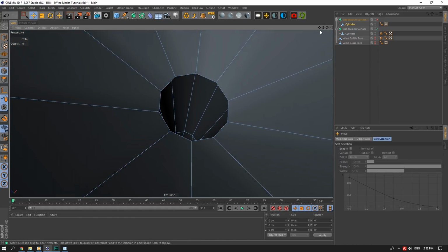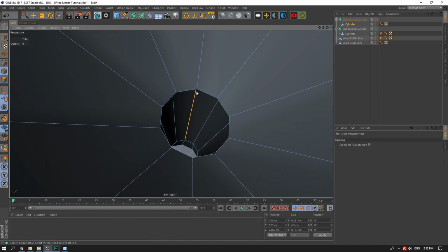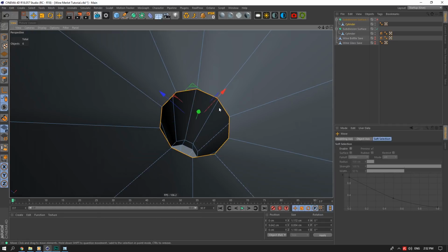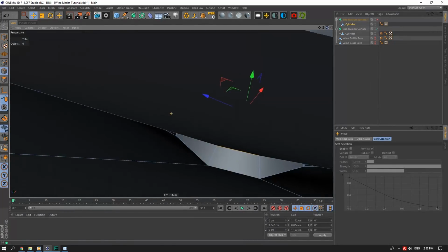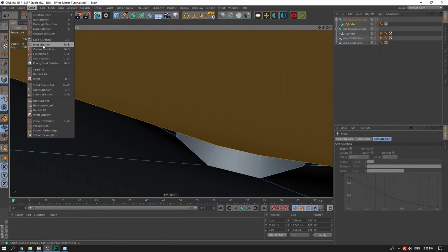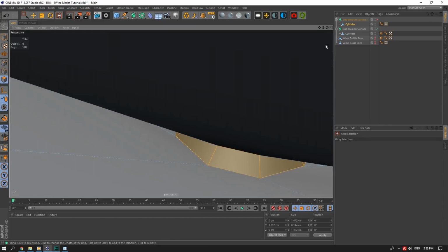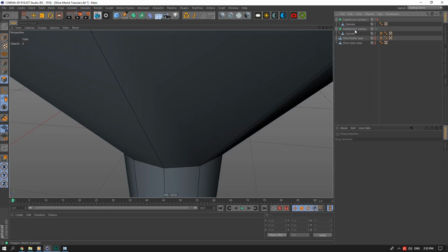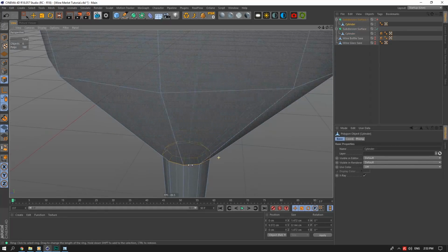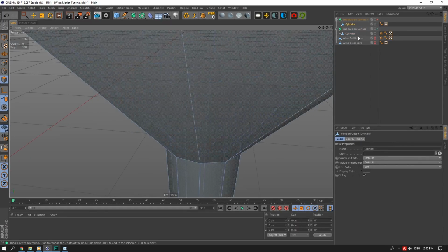Before, I used to right click, close polygon hole, and then stitch them all together. But what I found is actually better. Let me get rid of these extra faces first so I can give you a better visual representation. These inside faces, you do not want them there because that will really mess up your final render and you won't know what's going on. So delete those.